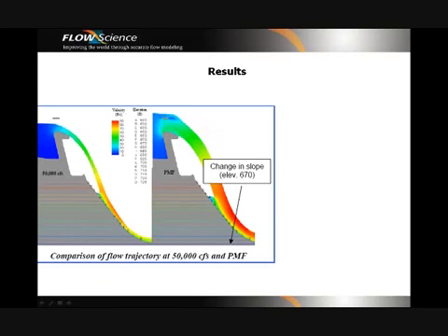It was found that the trajectory extended 5 to 10 feet vertically down the spillway past the impact point observed at 50,000 cubic feet per second. The impact location was still 30 vertical feet from where the change in the catch chute begins, which is well within the region of the chute that was designed for the water impact.